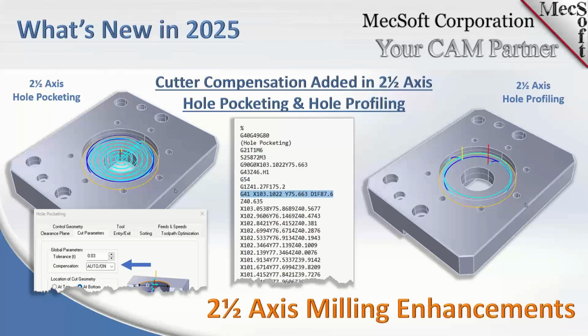One of the main things we added is cutter compensation for hole pocketing and profiling. If you have a hole that you need to cut with very tight tolerances, hole pocketing and profiling is the way to go.